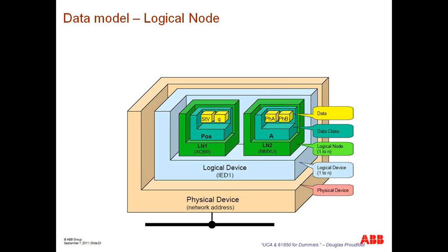Question came in. Are there any primary devices, breakers, transformers, that can send GOOSE messages on the market right now? We really want to keep the webinar educationally oriented, but the answer is there are indeed available in the market primary pieces of equipment that have electronic interfaces that can subscribe to GOOSE messages.